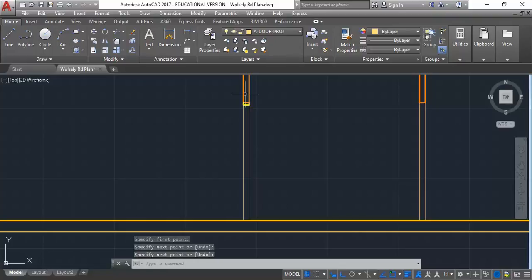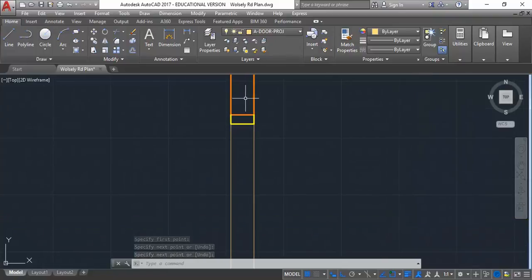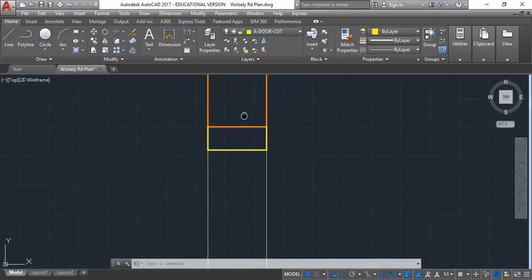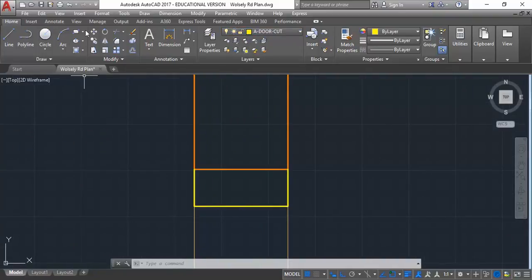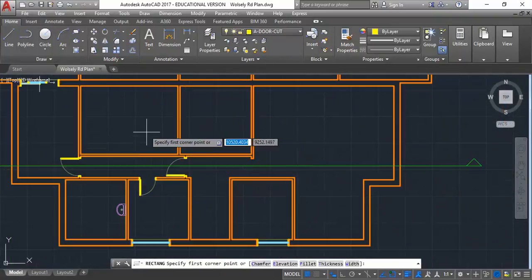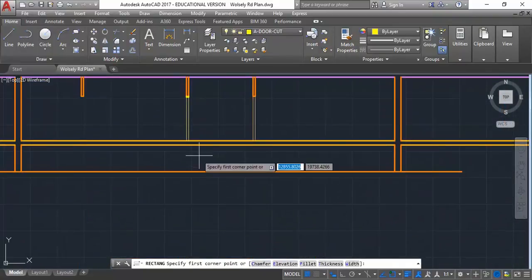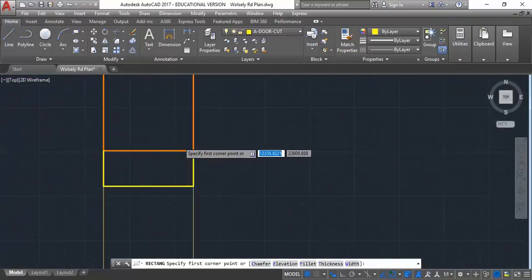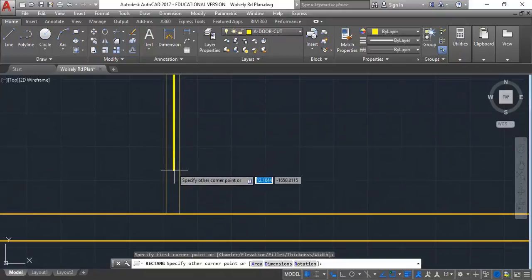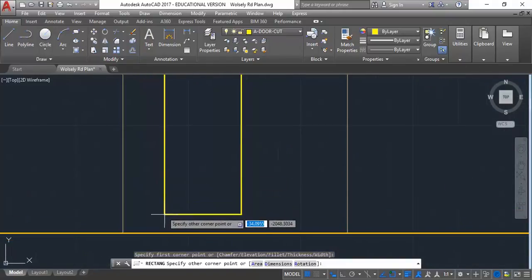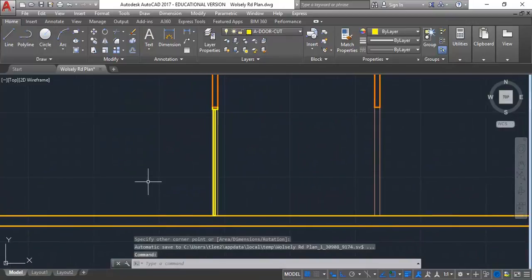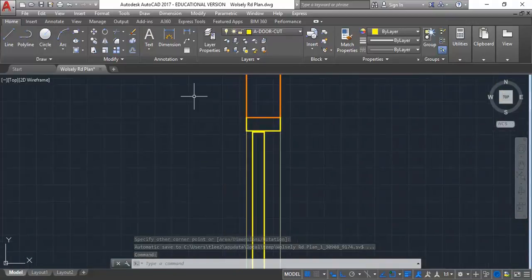And maybe I'll just real quickly show you how to draw a door because it's really easy. You could just do it by eye almost with a rectangle. Make sure it's on the right side, so it's going to be on the left-hand side. You would just draw a rectangle inside. It looks something like that. Okay, if you want to see the door in section as well.